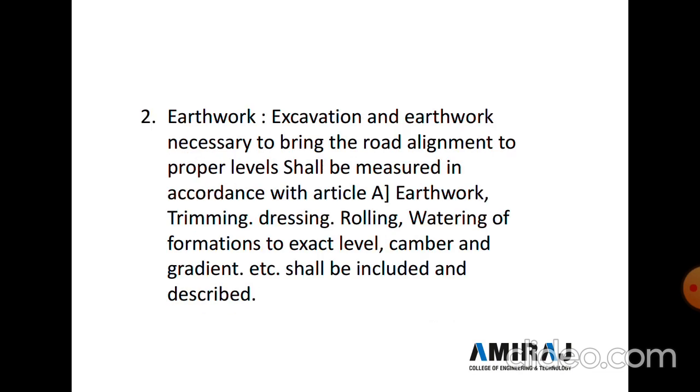The next type of road work is earthwork. Excavation of the earthwork necessary to bring the road alignment to proper level shall be measured in accordance with the relevant article. Road trimming, dressing, rolling and watering of the formation to exact level, camber and gradient shall be included in dressing.